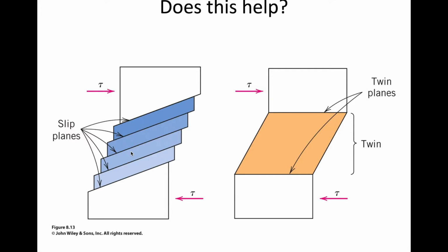So with light microscopy, we can't see a single dislocation, right? A single dislocation is on the order of the atomic spacing, and so we're not going to see that on a light microscope. But what does happen is that slip will occur on certain bands and cause the shifting of a certain subsection of the crystal, right? Like this. And so you'll see this sort of step feature in this. And so these are the slip planes that are being active.